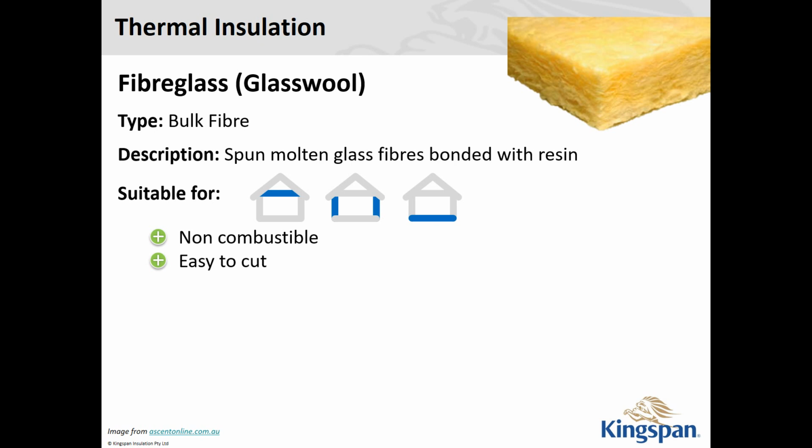It might be a little bit expensive compared to other materials. No, this one here would probably be more cost effective. It probably works out to be $7 or $8 a square metre. That's why this one's more commonly used in the building industry. It's pretty cost effective and gives you the R values you need. In most houses at the moment the studs are generally 90 mil thick, so it's made and fit for purpose.